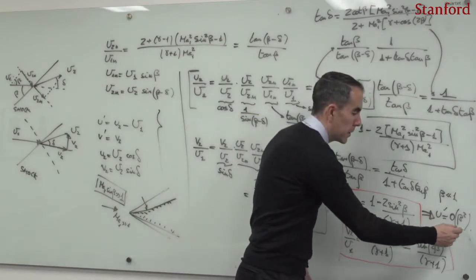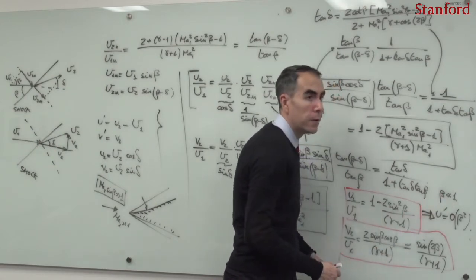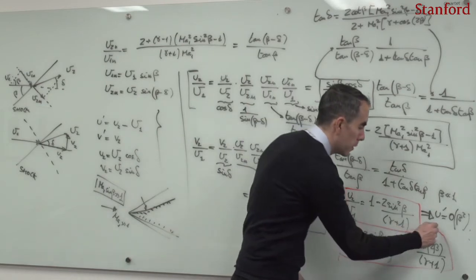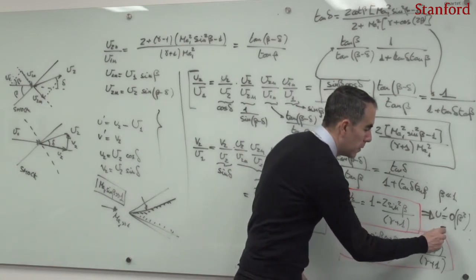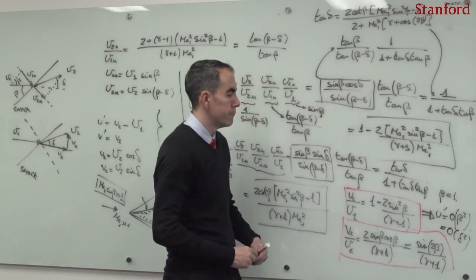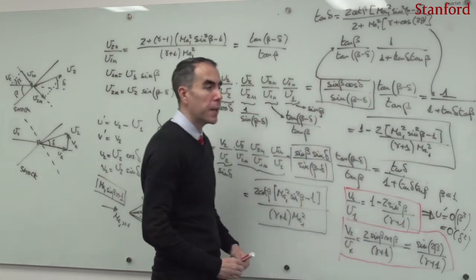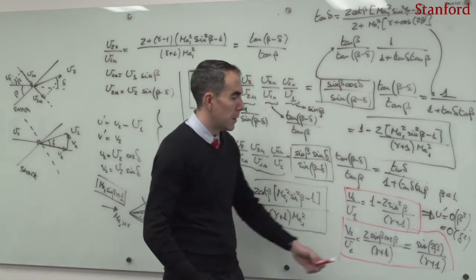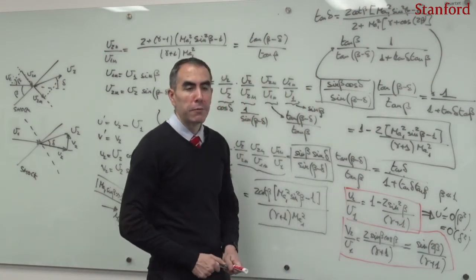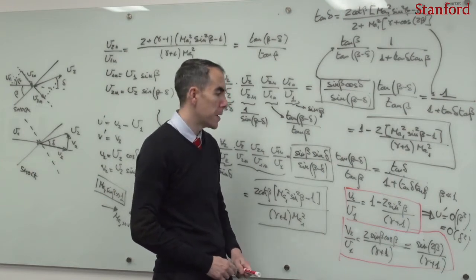So if beta, remember, if the Mach number is large and beta is small, then beta and delta are similar, as we proved in the last lecture. And as a result, this order of magnitude here becomes of order delta square. Well, that this velocity disturbance in the horizontal direction becomes of order delta square is actually important for the theory of hypersonic flows over slender bodies.